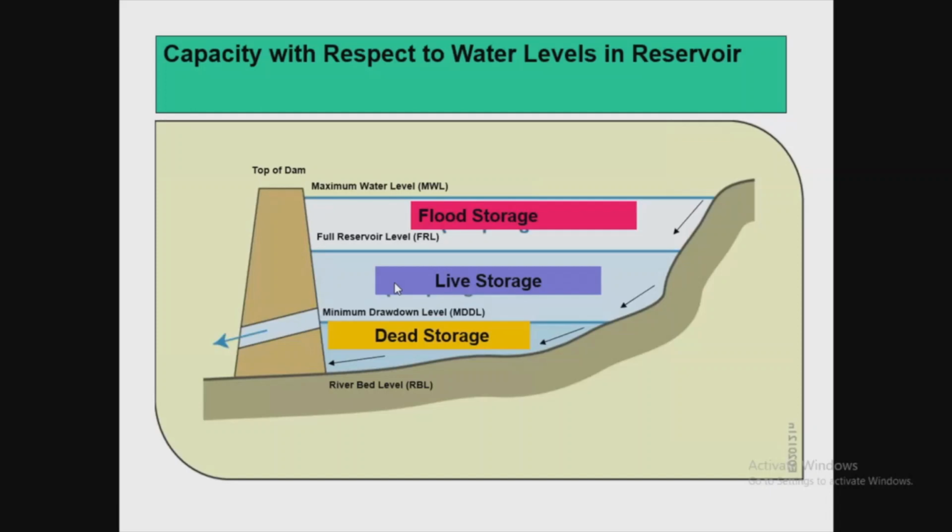So what you have to do is assess your capacity previous to allocation, whether it is encroached or not. I'm not telling you to assess every year. You have to assess at least every 5 years, or at least every 3 years. If you are in a gorge portion, a steep portion, it is better to assess every year. But if you are in a different zone where sediment transportation or sediment rate is less, you can assess in 10 years also. But in hilly areas or landslide areas, you have to assess every 5 years, at least every 3 years, the capacity of the reservoir.